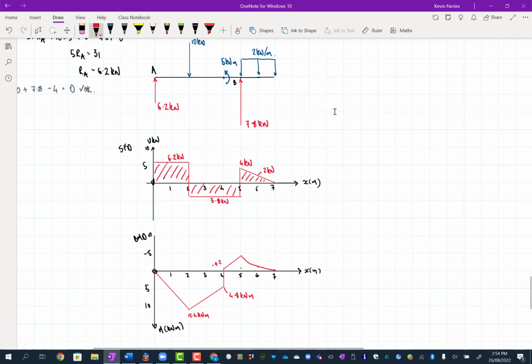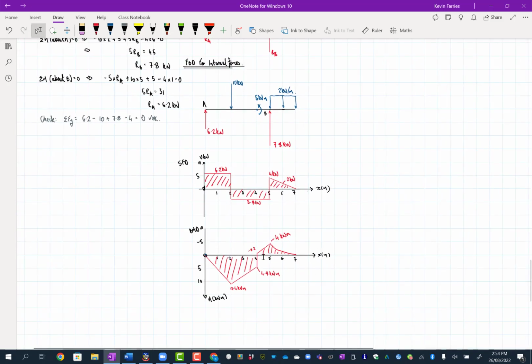And that's just got the bending moment diagram. I just need to write what that is, and that's 4 kilonewton meters. Then we shade that, and we're done. And we could check a couple of sections, bit of a complicated one, so you might want to do method of sections and check a couple of sections for that to make sure you've got the right answer. And similarly, when you get stuck, if there's something that doesn't look right, just take a section at that point, figure out what it should be, and then try and figure out where you've gone wrong. Okay, done. Whew.